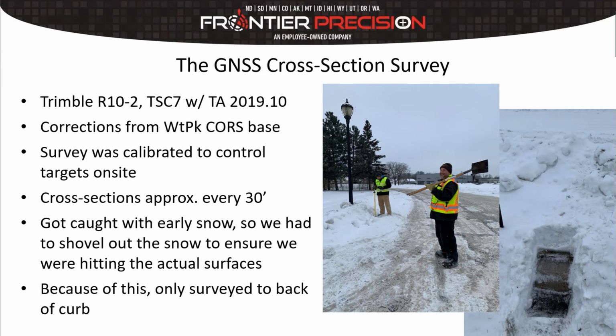And then we did cross sections about every 30 feet. So you can see we got caught with the snow. That's me with the rod in the background. And some of you may know who Tony is, one of our other AGEs here in St. Cloud. He was there with his shovel and his ice chisel and helping me. You can kind of see the picture on the lower right-hand corner there. We were chiseling out the curb and gutter to make sure we got down to the right surfaces. But again, because of this, we only went back of curb to back of curb, but we feel we got the necessary data for what we needed to do there.